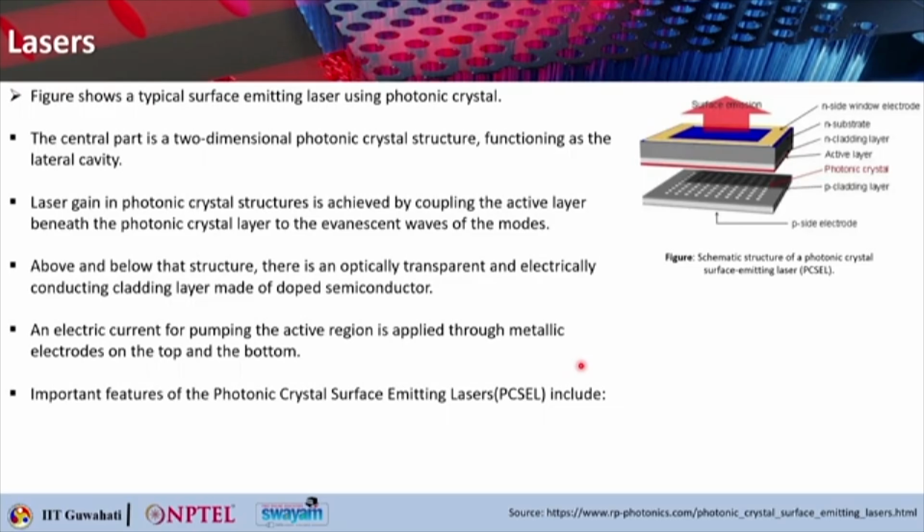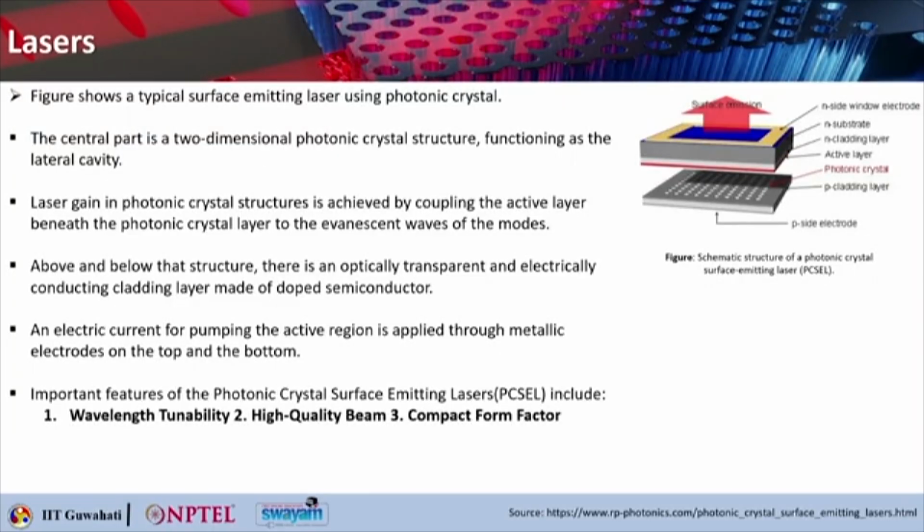There are some important features of these photonic crystal surface emitting lasers, which include wavelength tunability. Photonic crystal surface emitting lasers can be designed to emit light at specific wavelengths or tuned within a particular range, making them adaptable to various applications including telecom, sensing, and optical interconnects. The other important feature is a high quality beam. The use of photonic crystals enables precise control over the laser's optical mode, resulting in a high quality, low divergence beam with excellent spatial characteristics.